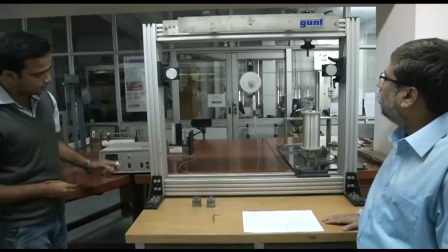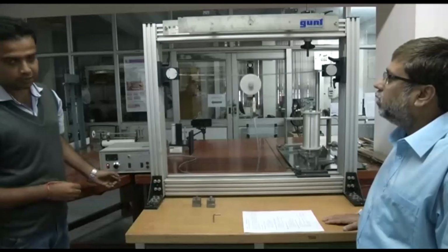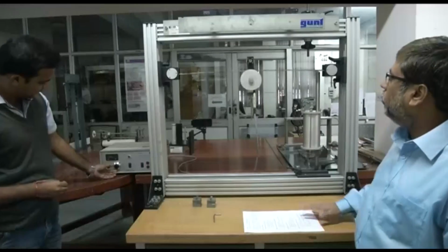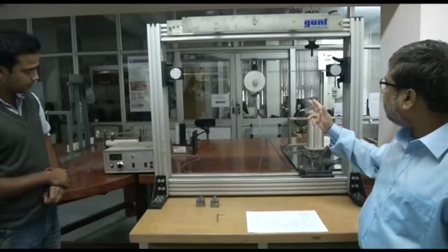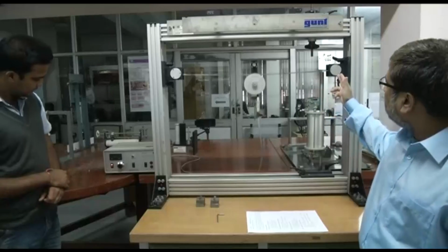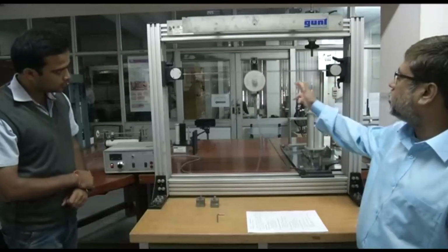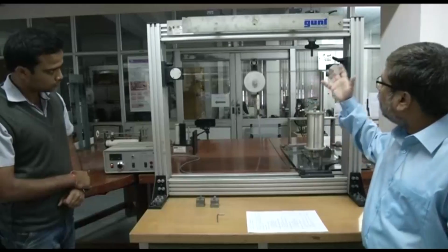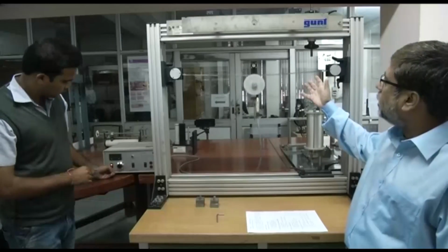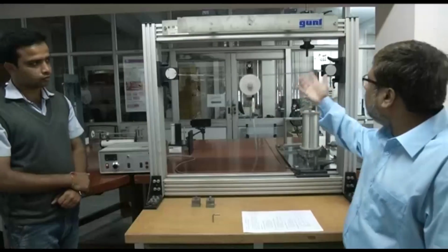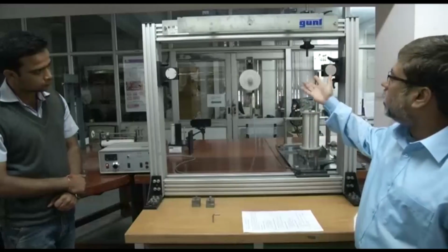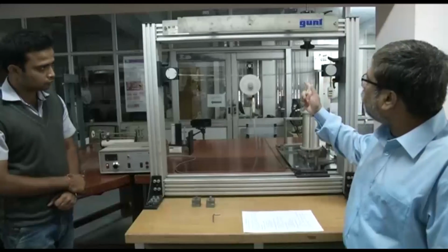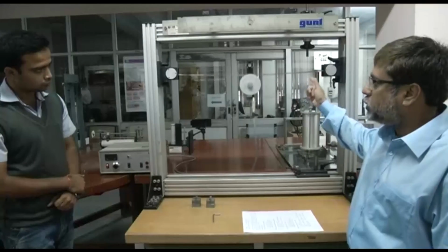Yeah, now you can see it is achieving that natural frequency. What is the frequency right now? 6.98. So we are right now at 6.98, we are approaching 7 Hz, and as you can see, the first mode of the beam vibration is becoming very apparent, and you can easily imagine that if this kind of excitation happens to any structure, any bridge, any machine, then naturally it would not be able to resist this vibration. So our motto will be how to resist this vibration amplitude.